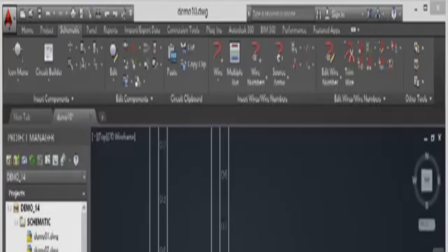The break type goes onto the layer Symbols, and you can list the layers if you want to and pick a different layer. I'm just going to click on OK now. What will happen now is I get my split. There's my split there, and I'm going to place it there. Now, where I've split that, you can see that I've got my jagged lines. If I zoom in, there's the jagged line there at the bottom, and there's the jagged line there at the top.